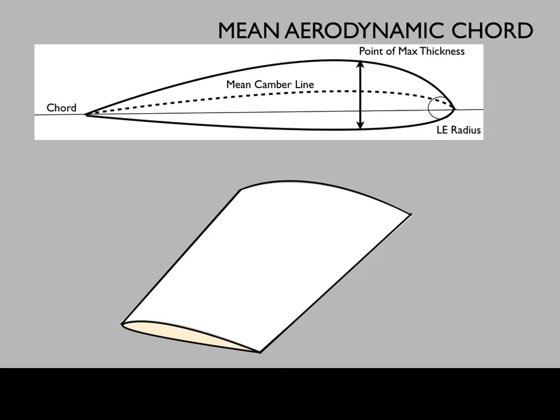Next important definition which I would like to explain to you is the mean aerodynamic chord. The chord line that passes through the geometric center of the plan area, or the centroid, of an aerofoil is the mean aerodynamic chord, and for any planform is equal to the chord of the rectangular wing having the same wingspan and the same pitching moment and the lift.